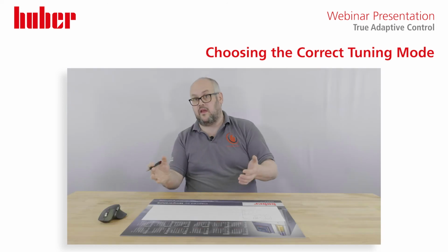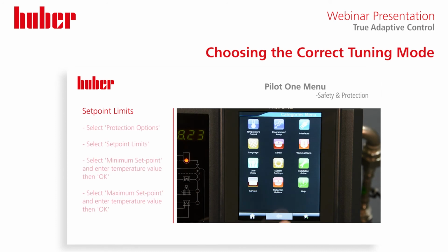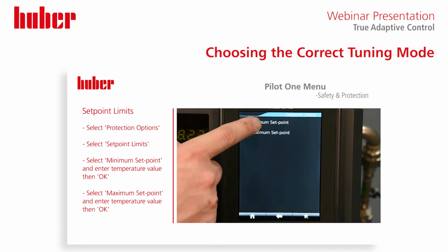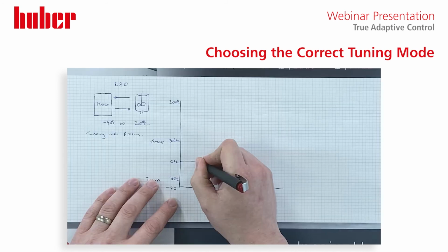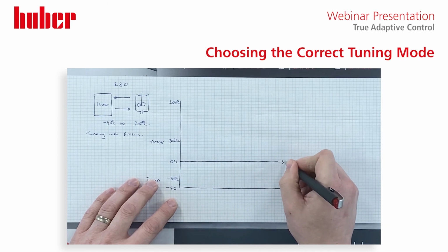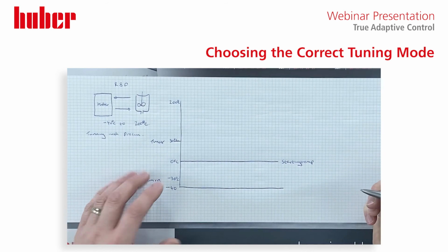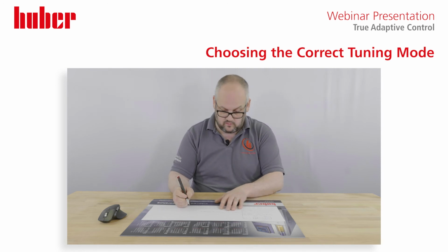We've done a video on how you can set your minimum and maximum temperatures. We'll put a quick reminder up here in an in-screen shot. So our starting temperature, we will go at 0 degrees C. Obviously, make sure you're not using water as your reactant contents if you're at 0 degrees C, because you will get ice.